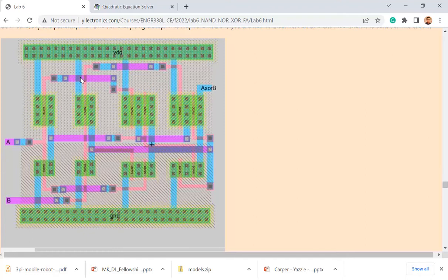Two vias. Yeah, it's got to be two vias. And I believe sometimes you can directly use the same spot for two vias, going directly up via one, via two. It might be fine, but I don't want to do that. Sometimes you couldn't see it really well for debugging purposes when you're looking at layouts. They're all on top of each other with different colors. But if you're looking at these vias, you clearly know that something like that is a metal one to metal two via, and something like this is a poly to metal one via. Right? As a metal two, then you still have to come down to poly.